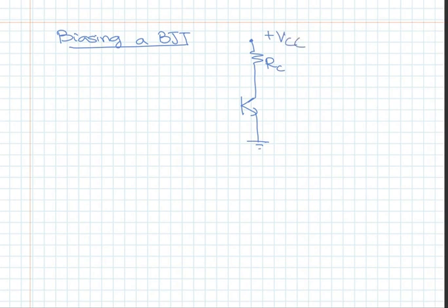And we want to see what happens if I connect a pure sinusoidal signal to the base through a resistor RB. So this Vin is a pure sinusoid, and I'm connecting it to this. I want to see what is the output at VC, which is Vout. Let's say this is the base, this is the collector, this is the emitter, this is the base emitter voltage VBE.